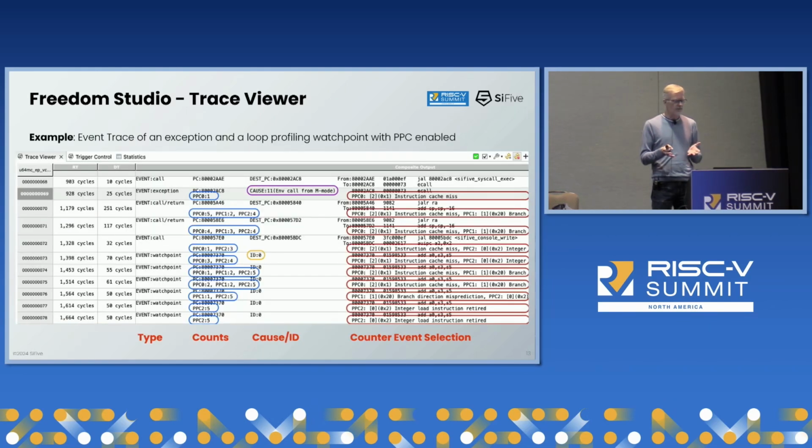The other thing is the profiling performance counters. Here I have an example where I've inserted a watchpoint into a loop. This is interesting because you can see that the PPC counters are counting up, for example, for instructions, for cache misses, and for branch misprediction.